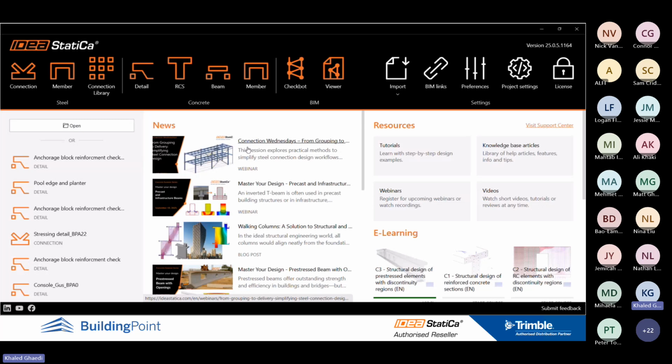And then for the transfer device, I can again go to the same DXF, and as you can see here, I can bring it in using this coordinate. But let me just go back there and take advantage of the template that we have. Okay, so we have the bearing plate. You can click on that. And again, if it's not exactly at the edge that you want, you can simply change the edge by going to the options. So for example, here I can put it on edge number 3.